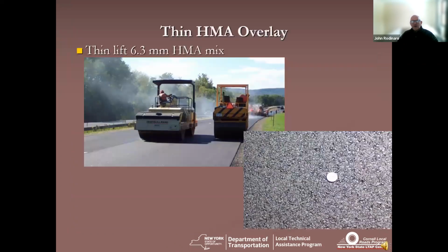And you've got an unbelievable armor coat. And then last but not least, our thin hot mix overlays. That's 6.3 mix that we've been using probably for 10 to 15 years at DOT, becoming very popular as a wearing course. And you can get it down 3/4 to an inch thick, as compared to 1.5 inches for our normal 9.5 and 12.5 mixes. And you get a beautiful surface. Like you see in the right-hand part of the slide, for any of the old timers, it looks just like our old 7F mixes.